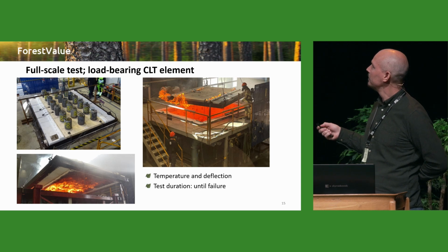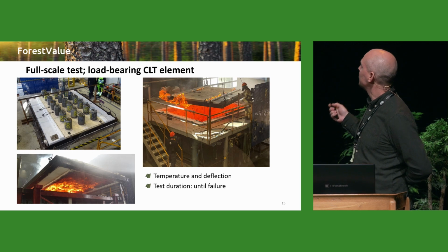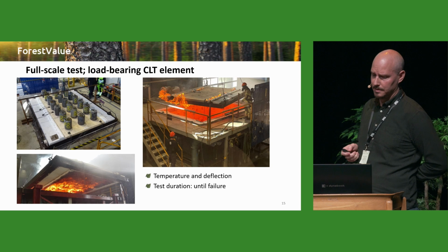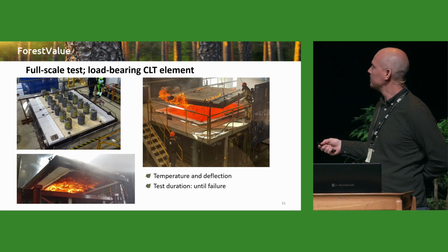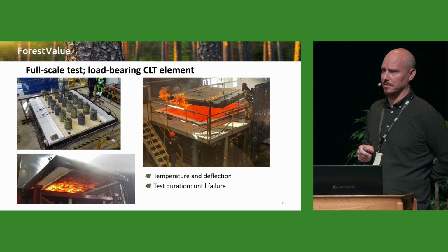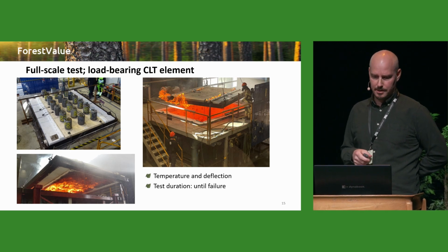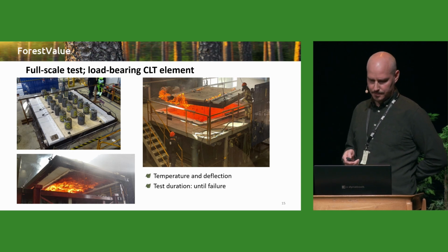It's loaded before the testing. And to the right and to the bottom, it's when we are lifting off after the test. The exposed side here to the left, you can see the underside of the CLT element. We ran this test until failure, meaning that they were breaking. And it was almost 2 hours test.